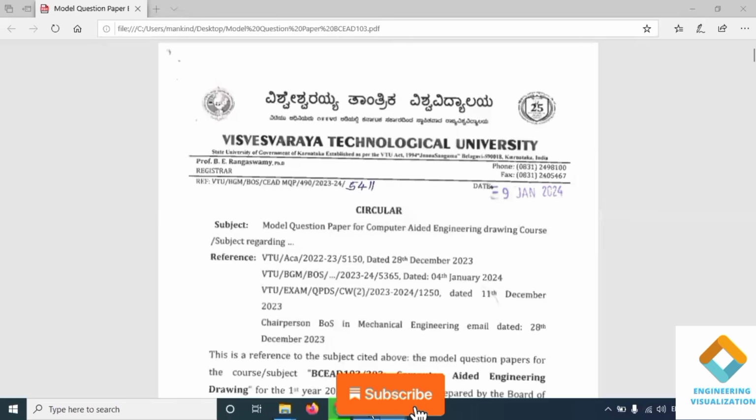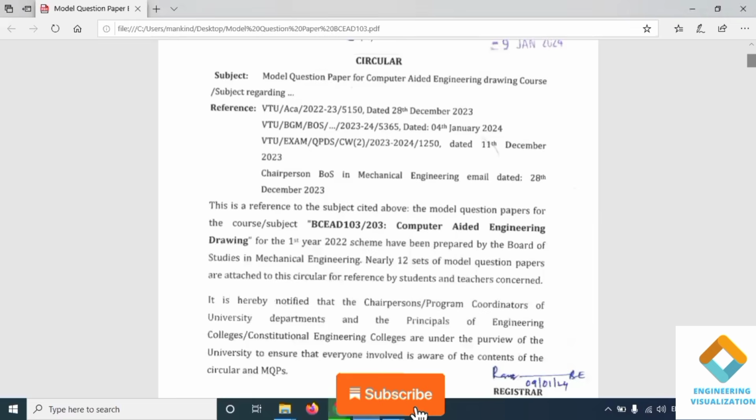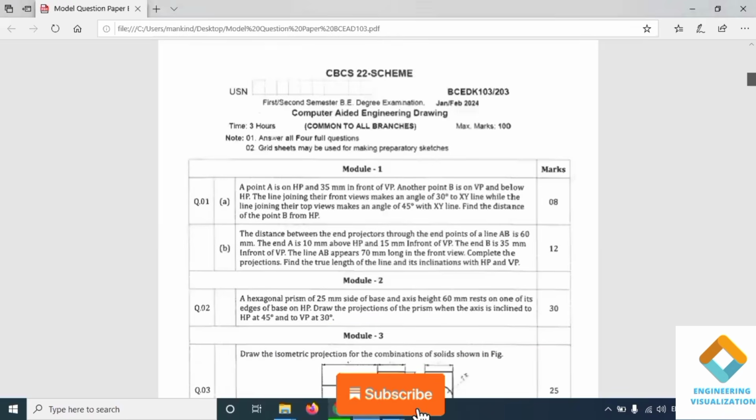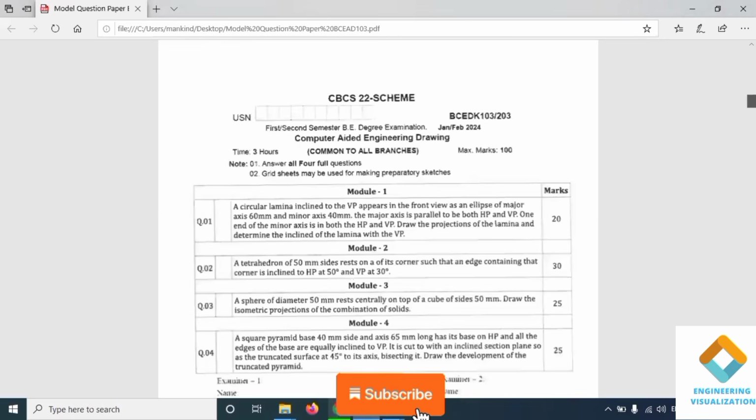Welcome to the engineering visualization channel. Today we are going to solve problem number 2 in model question paper 2 of computer aided engineering drawing. It will be beneficial for you if you watch this video until the end, so that you can understand each and every step of this problem. This is one of the important problems, projection of solids, tetrahedron. A tetrahedron of 50 mm side rests on one of its corners, such that the edge containing that corner is inclined to HP at 50 degrees and VP at 30 degrees.